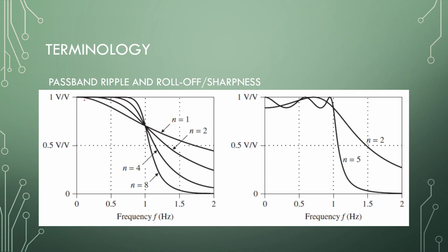For the other filters, you will see that if the order goes higher and we increase the Q factor, we can maximize the passband. They all cross at the same point here at the minus 3 decibel point, or 0.707 volts per volt. As we increase the order of a filter, it becomes closer to the brick wall approximation that we actually want.